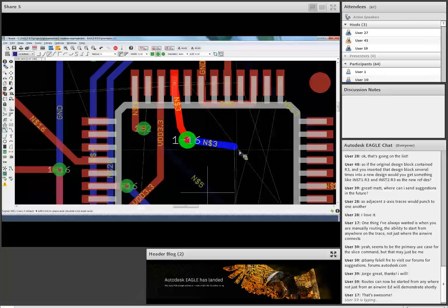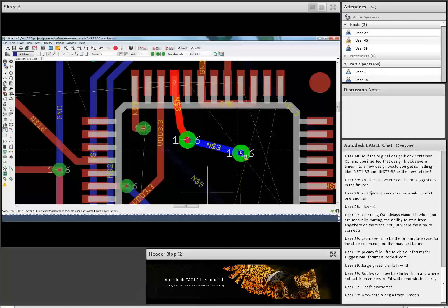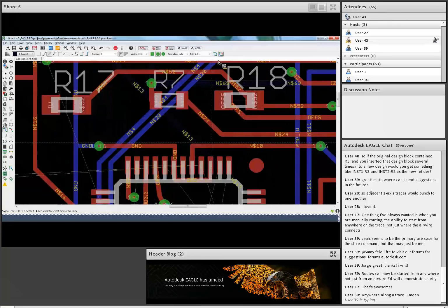Now, if I press the shift key and hold, and now I hit the space bar, look what happens on the status bar right here. It will go through the same layer selection, but in reverse. So it'll start from the bottom layer and make its way up. So if you're working with a design that maybe has 16 layers or 8 layers, instead of always going in one order, you could go in either order now as well.